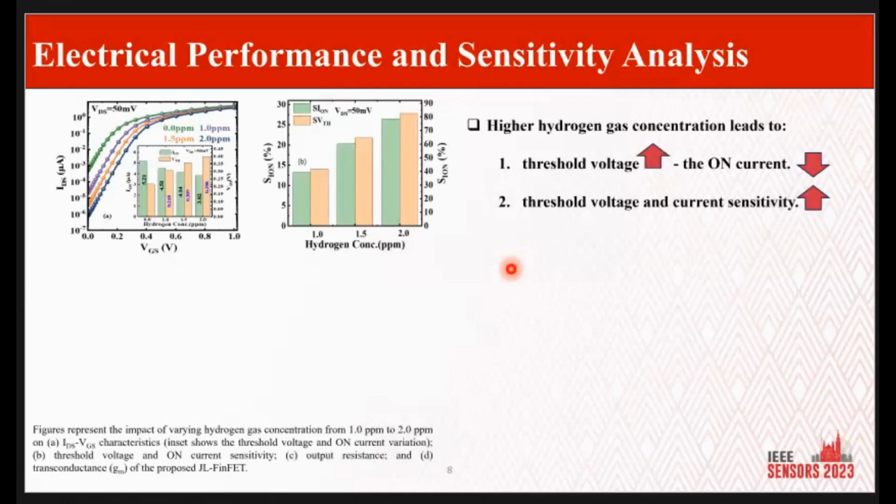So if I take current compliance here, 10 to the -3 current, what I'm going to see is when I don't have any charges, the current is here, and the threshold voltage is here. When I increase the amount of charges in the gate, I'm pushing to higher voltages because I need to increase the voltage more to get the current, because I'm screening the channel. And what you can see here is the voltage threshold is just moving slightly to the right. This is represented in bars here. It's exactly the same thing.